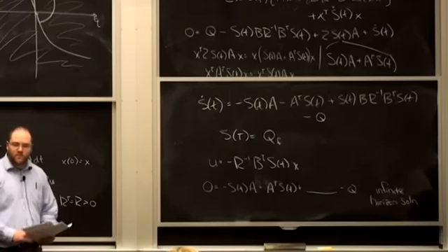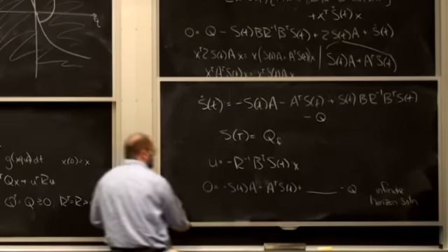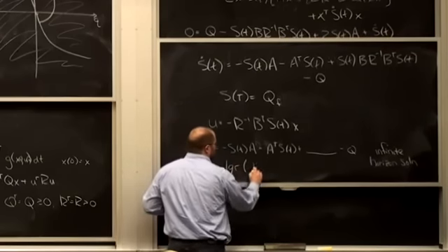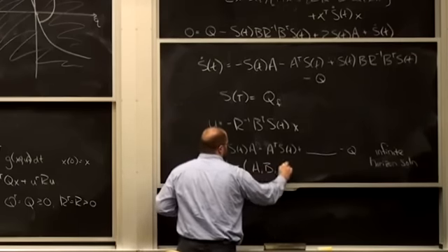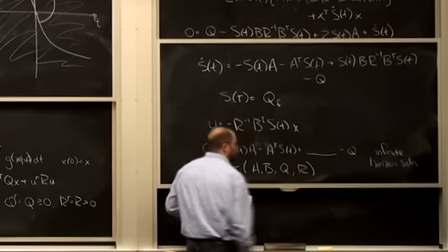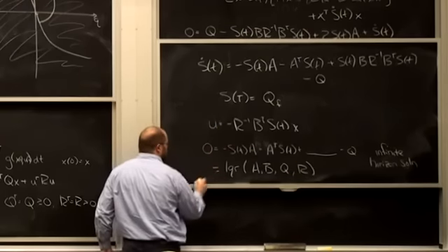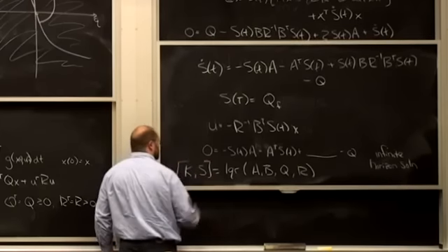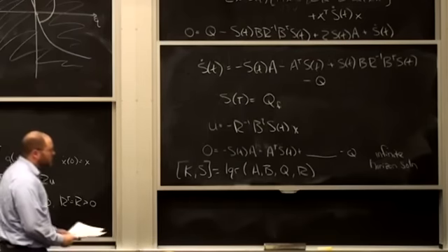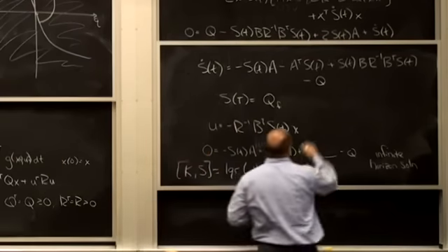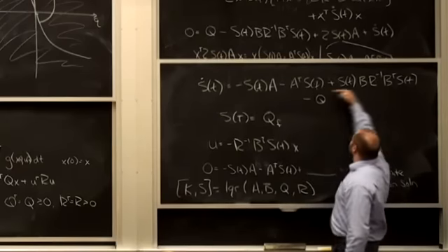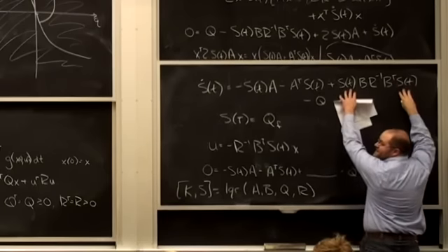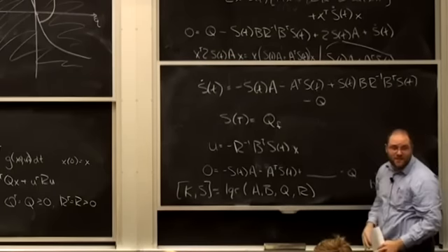If you open up MATLAB and you type LQR(A, B, Q, R), it's going to output two things. It outputs K and it outputs S. Solving this thing is actually not trivial. So how do you solve that for S? The hard one is it's got this S in both places.